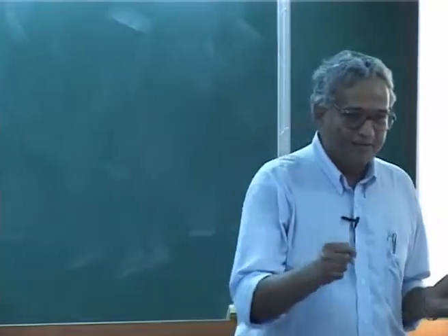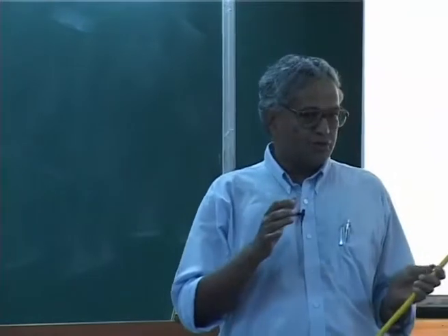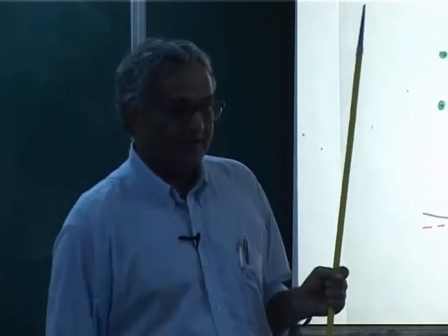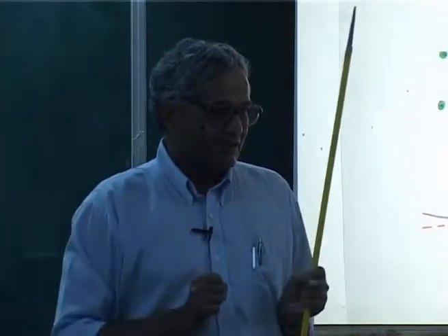because if you do one, in the sense if I want to climb up, very simple, but because of the increased lift, or we call it thrust, the torque will increase. As a result, the helicopter will start turning. That means he has to control. Okay.